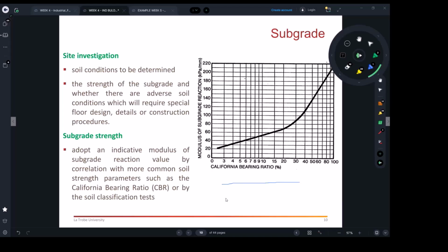So again, if this was our industrial slab, let's say it's 150 thick. This is the concrete industrial slab, say 150 thick, and there is a point load. How does it work? The point load will be distributed by 45 degrees over the concrete. When there is a load from the post, the load will be distributed by 45 degrees. That's just the rule of load distribution, 45 degrees.